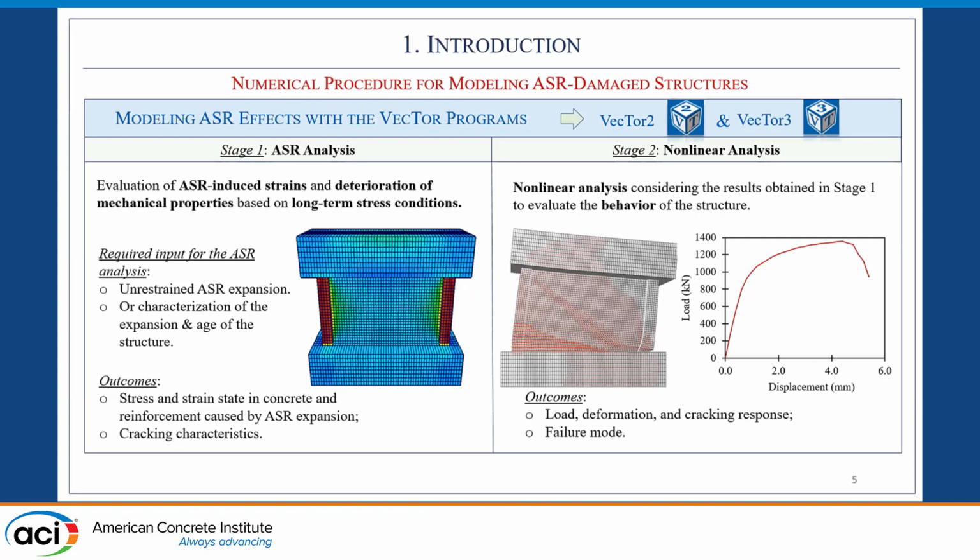And then for our structure, we perhaps want to know its residual capacity, its failure mode, crack pattern, deformation response. So we can use the results from the first stage of the analysis to perform a nonlinear analysis and investigate all these behavioral parameters that we're interested in.